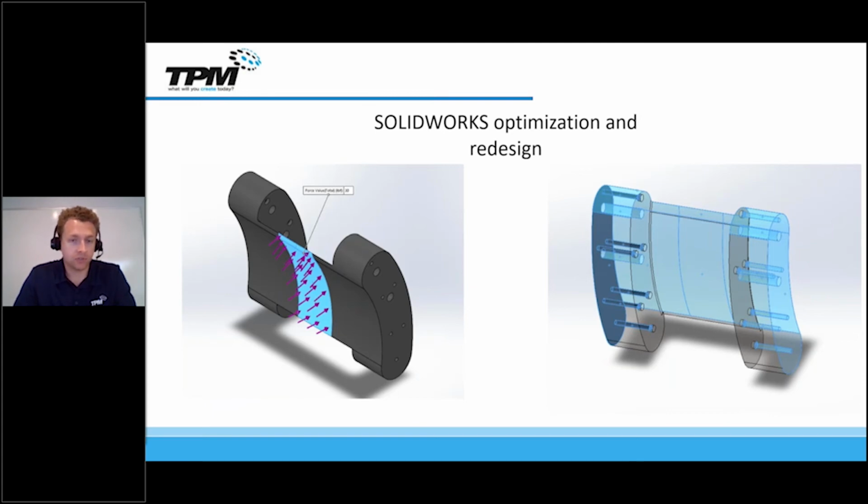One of our problem statement goals was that we needed to maintain all of the fastener holes. So you can see in the picture here on the right, all of my socket head cap screw holes are maintained and some of my larger dowel holes. All I have to do is select them in SOLIDWORKS and they're maintained. Okay, the only thing left to do for the setup is to set the overall factor of safety to 1.5 as the goal for the simulation. This parameter allows for SOLIDWORKS to remove as much material as possible until the lowest factor of safety in the entire part is 1.5.